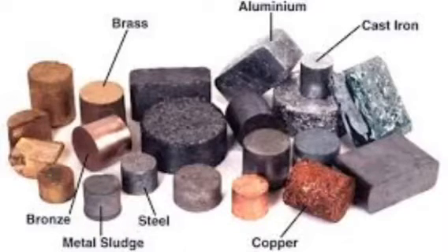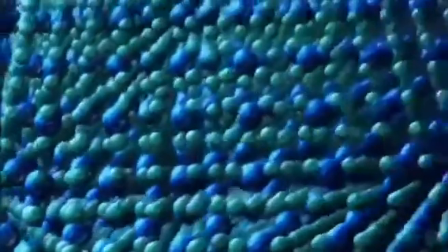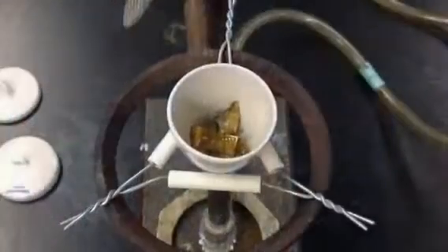Here's an example when tin is added to copper. Adding tin to copper during melting changes the properties of the metal. The larger tin atoms restrict the movement of the copper atoms, making the material harder. A blow causes the atoms to vibrate, but the tin prevents them from moving too far out of position.